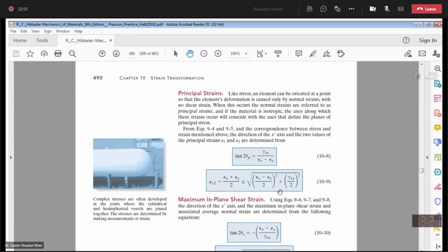if you recall the figure which we drew, the triangles, we said that tan is positive in the first and third quadrant. Okay? And then we also calculated the resultant. So basically your principal strain is the average strain plus minus the resultant. Principal strain is average strain plus minus resultant.